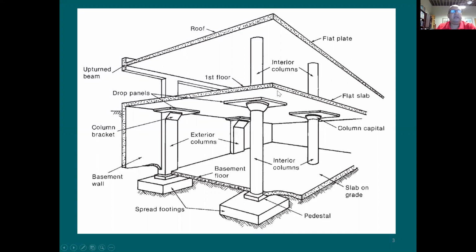Now I want you to think about putting lots of loads on the roof. Just put some loads and see what happens. This load wants to push this slab down and also wants to push this slab down. Now you have the potential that this column is going to penetrate the slab, and we call this punching. You don't want this column to punch through the slab. Otherwise, it's going to be a mode of failure. It's going to be a collapse. You don't want to see this.